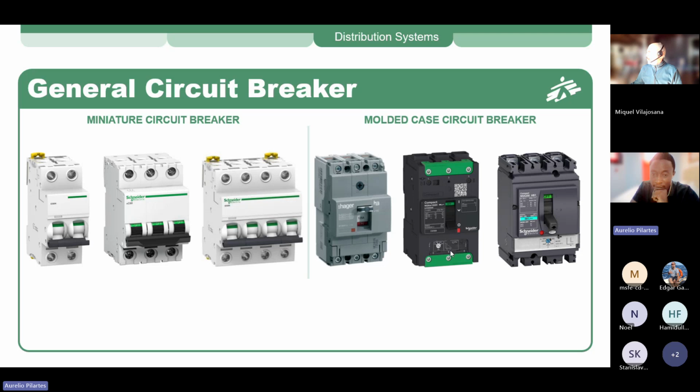Apart from that, because they are completely regulable, with some more advanced MCCBs you could even choose the tripping curve. You can make it work as a C-type circuit breaker or B-type circuit breaker. And for the ones that are combined with RCCB, because some of them can be combined, you can also set the RCCB part, even the reactivity, how long it should delay before tripping the circuit. So these are the main differences between an MCB and an MCCB.